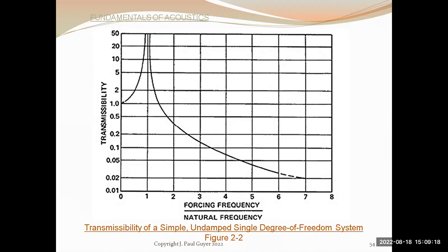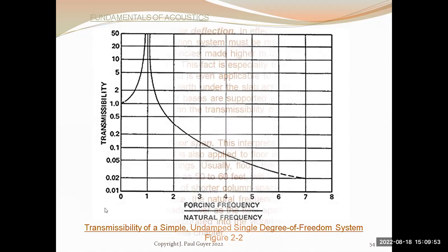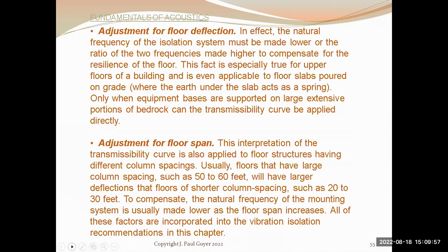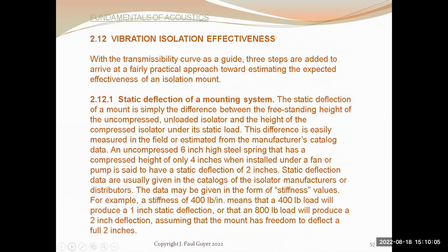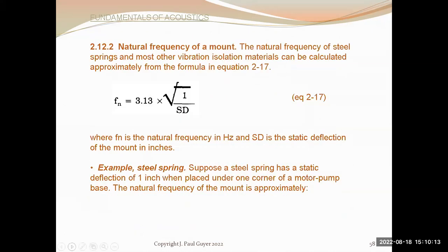And if you are right on the natural frequency and continue to apply the forcing frequency at that natural frequency, the amplitude of oscillation of the mechanical or structural system just continues to increase and increase and increase until finally the system breaks. So it's something to be avoided, and it can crop up when it's least expected, resonance. So one interesting little example as far as resonant frequency is concerned.